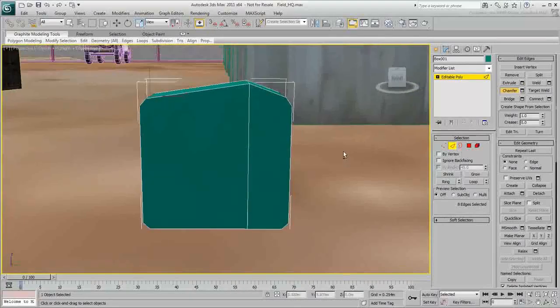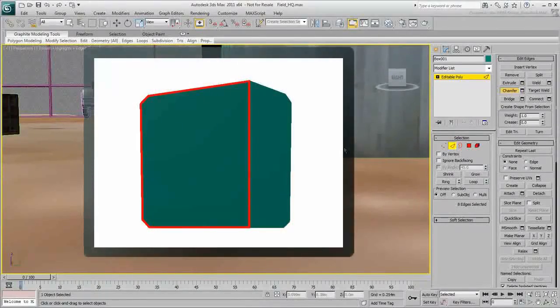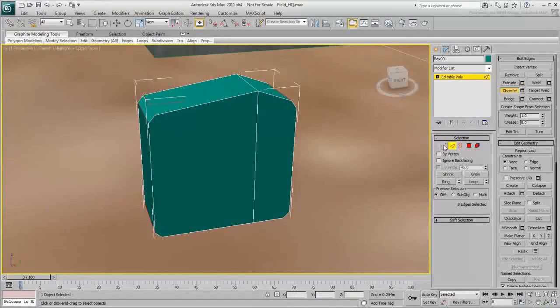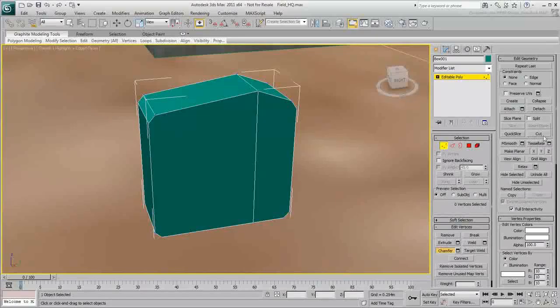The corners look good, but chamfering created 6-sided polygons, which can be a problem. 6 is an even number, so you can divide each 6-sided polygon to obtain quads. Select the vertex sub-object level. Turn on Cut mode. Place the mouse directly over this vertex.